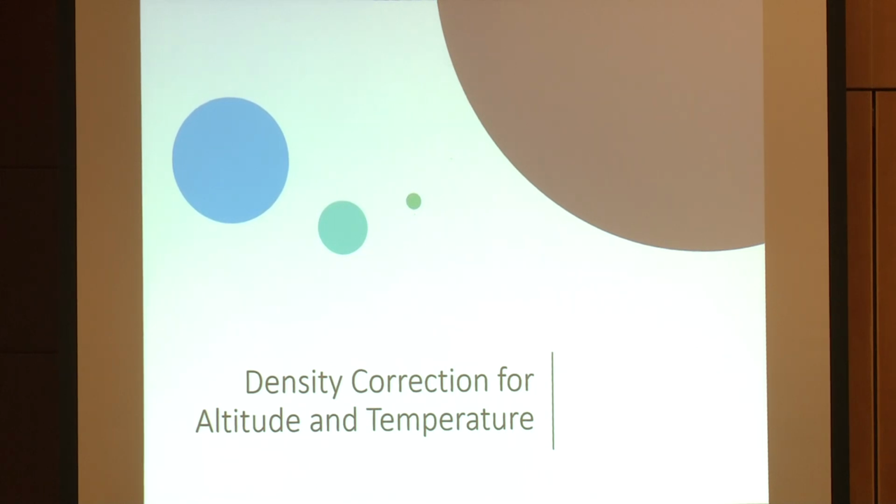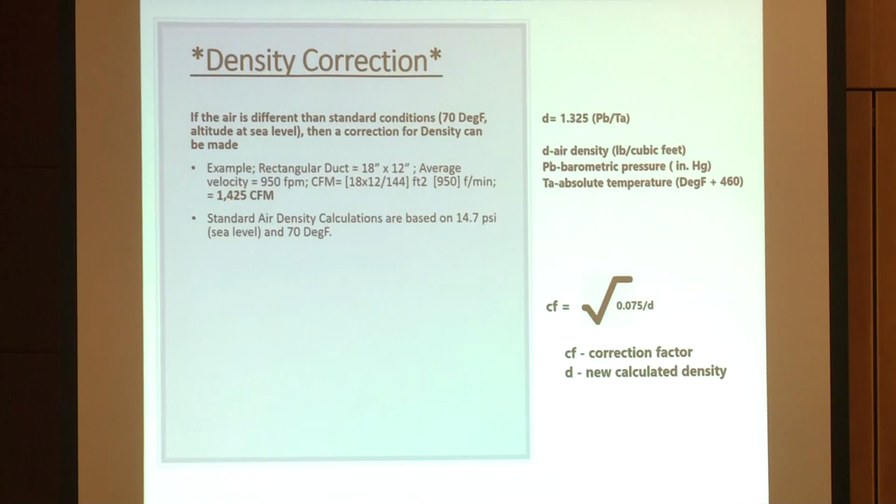So now you have all your measurements, you have your CFMs, everything's working fine. And of course, if you're here in Bangkok or you're here in my town of Tampa, we're basically at sea level, right? We're not very high. So we don't really worry about density corrections. But if you're in an area that needs density corrections for CFMs, if you're in Denver, Colorado, or you're in Bogota, Colombia, now you've got to look at 7,000, 8,000 feet of height.